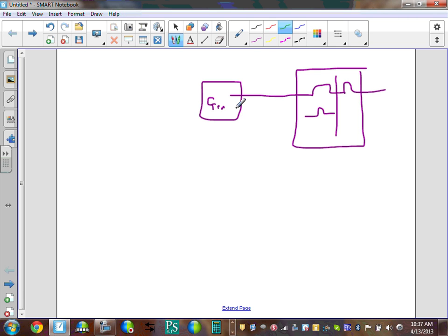So then this wire right in here, coming in with the gen and tied to inside, that's the ground bar. That wire, guys, like we said, is called the supply side bonding jumper. In this case, bonding jumper. That's typically if you have parallel switchgear. That's what you do, because you don't put the circuit breakers right at the generator. You don't want somebody to trap them.